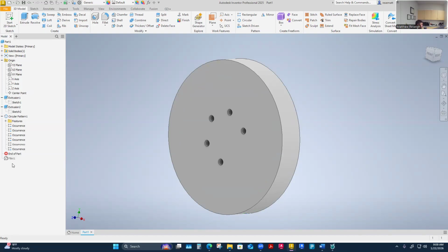Clean up my files and not just have suppressed steps that I don't need anymore left in here. I feel like that's part of doing good part cleanup at the end, especially when I'm working in a drafting environment where we're working with library parts and shared parts on assemblies. I would not want to give somebody this part to share and say, oh yeah, just turn off whichever ones you don't want. It's like, no, how about we make this be what we want with active features.